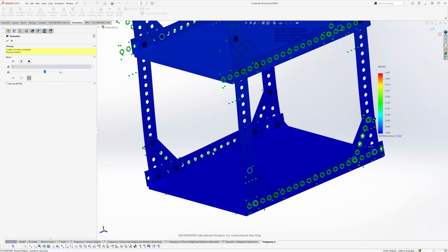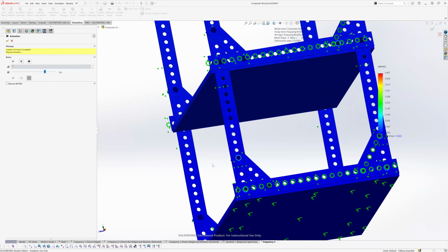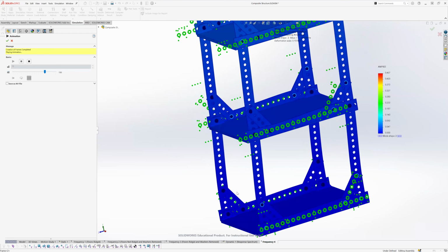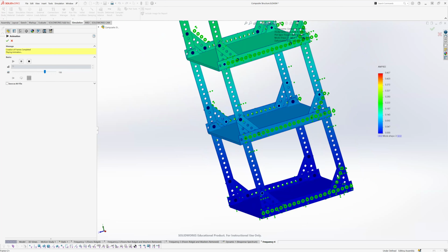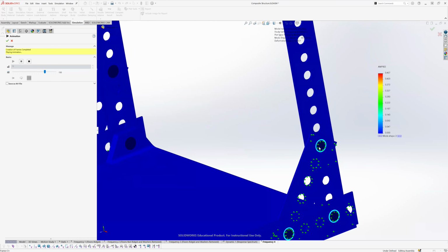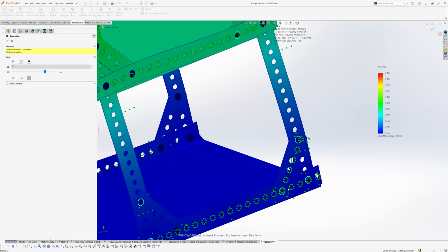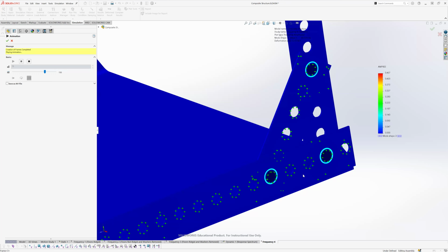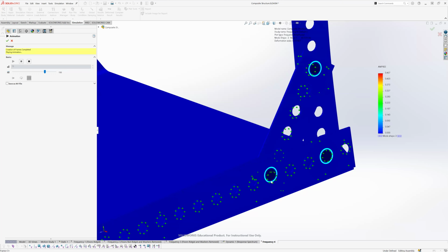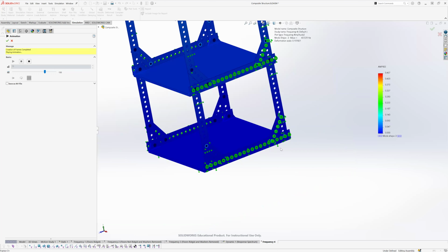This mass is moving a little bit, but this mass is not moving a lot. Obviously, the base is rigid, so that's not going to move either. Then another thing to check here is the pin connections, making sure that everything is working as I would expect. You should have rotation about all of these pins, and it should be